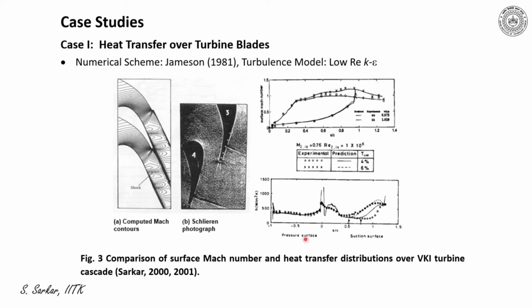Furthermore, I have evaluated heat transfer for different free stream turbulence levels. I have considered the turbulence level as 4% and 6%, and it has been seen that at 6% the prediction is very good. It compares very well on onset and end of transition, illustrating the augmentation of heat transfer on the suction surface.